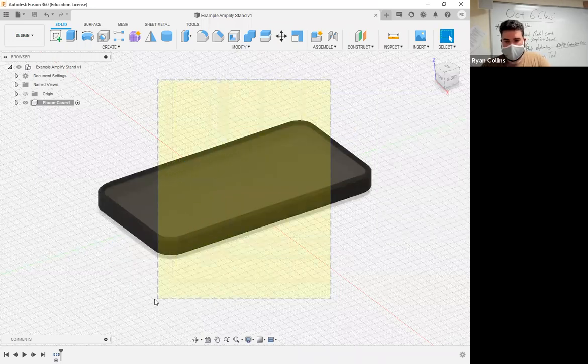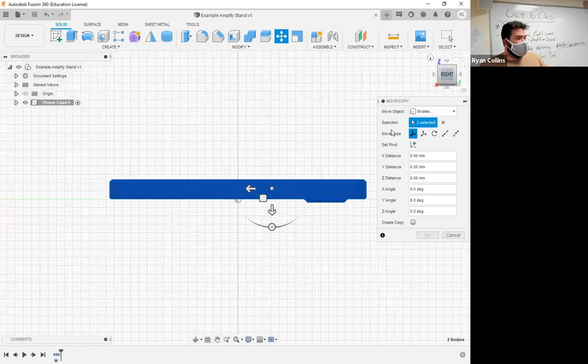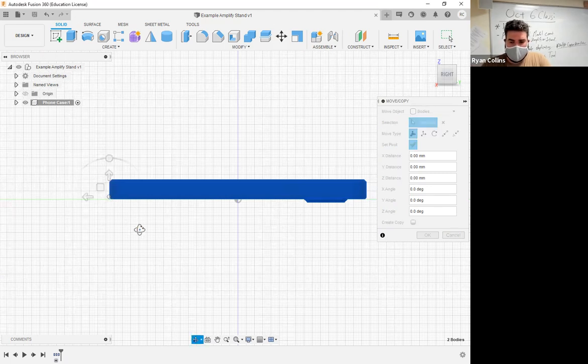Okay, reselect, move. Now what you can do, if you want to move an object or rotate especially, rather than from wherever it's clicked, you can select a pivot point. So what you do is the fourth row down here on your control box, set pivot, select there, and then I'm just going to go somewhere down that way.